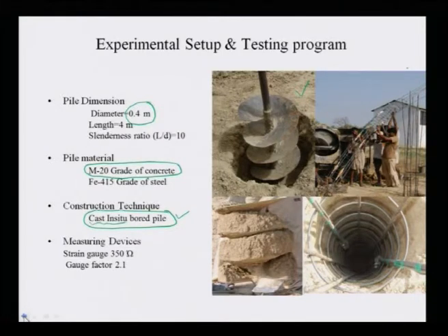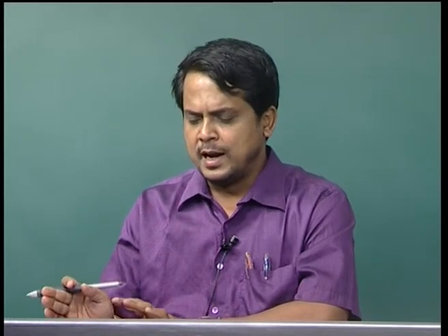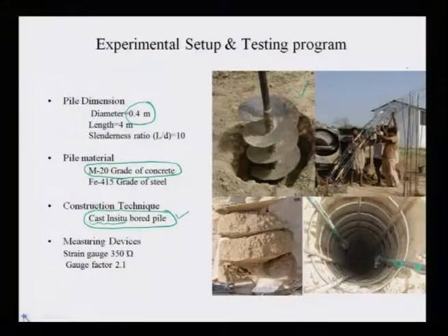The moment I say it is a cast in situ bored pile, that means everything has been done in the field: boring, casting, placing the pile inside the borehole, and placing the concrete inside this borehole. Everything has been done in the field. Sometimes people also place strain gauges inside this pile. This is one part of the research.